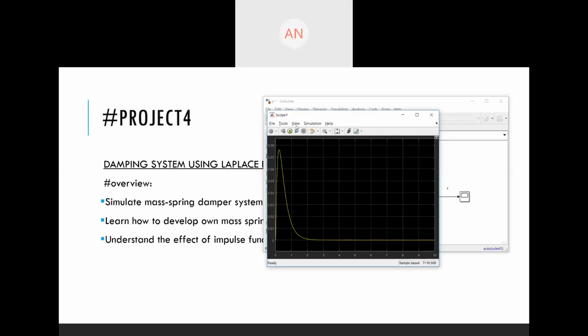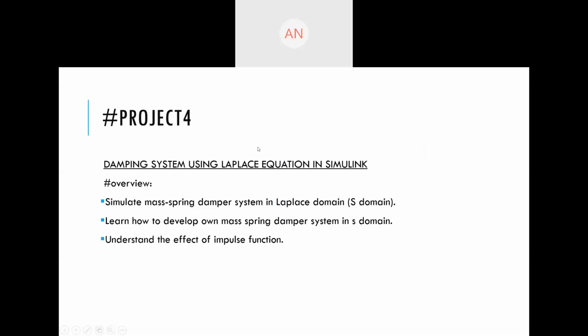Simulink. After this project, you'll be able to know how to simulate a mass spring damper system in the Laplace domain, which is the S domain, learn how to develop your own mass spring damper system in the S domain, and understand the effect of the impulse function.